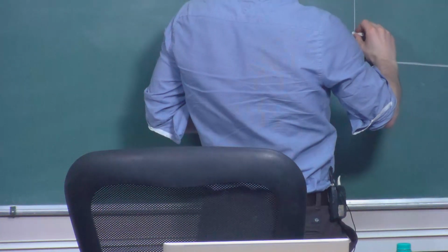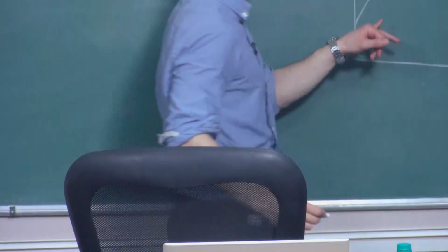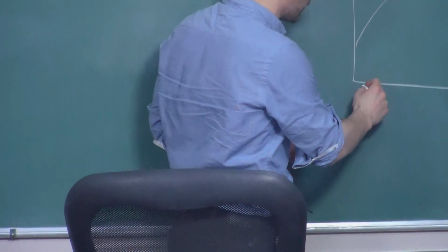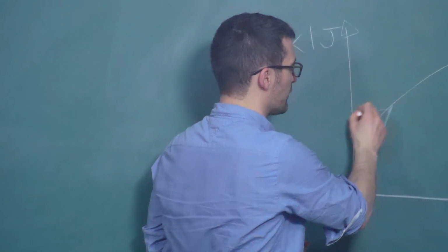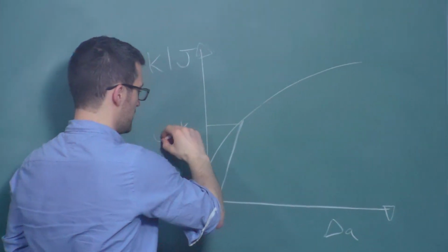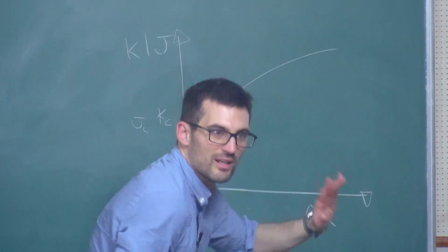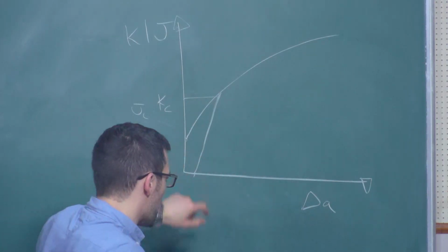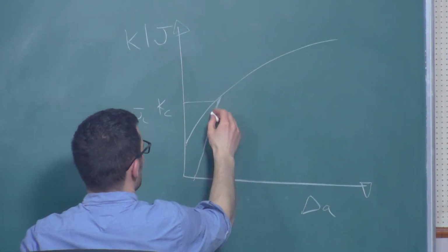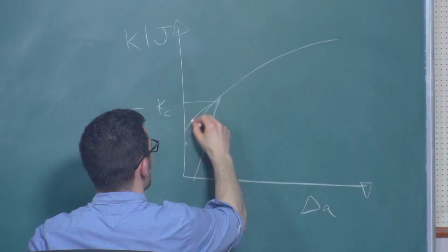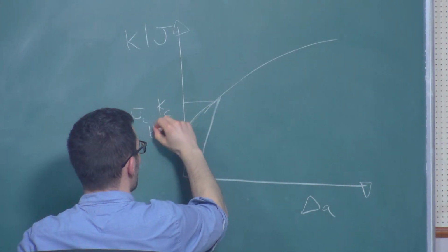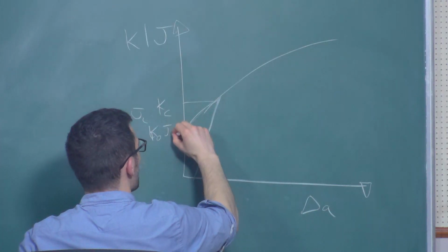If you plot a metal, normally people plot K or J versus crack extension. It will start somewhere at a point here and then rise like this. This is what it looks like. In fact, most standards like ASTM will tell you to pick the 0.2 value, which will give you the toughness. Or it could be GC as well. This will give you the toughness. So metals do exhibit that kind of behavior. Fracture will initiate at a given initiation toughness, which is typically a bit closer, like this. So metals do initiate at a given initiation toughness that the standard sometimes calls K0 or J0.